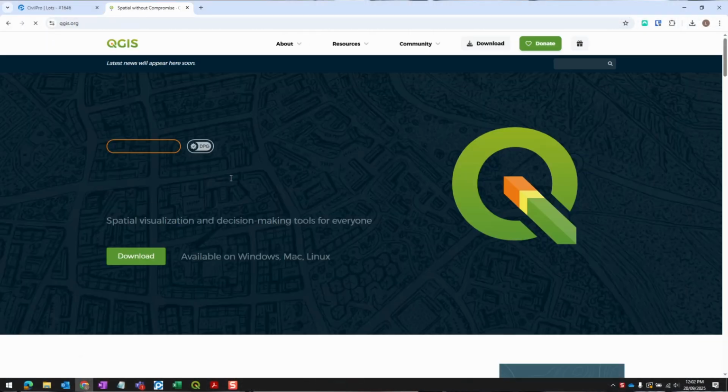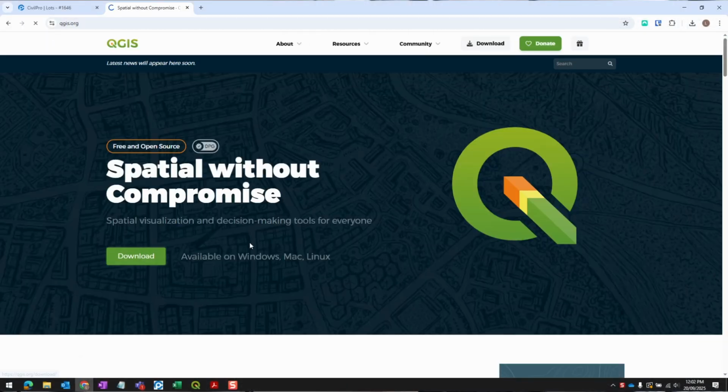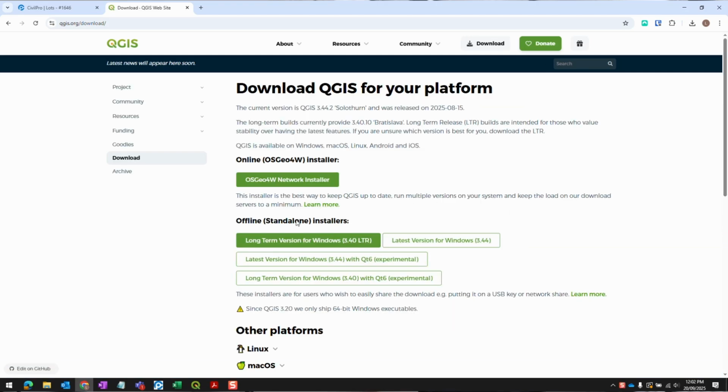I'll also be using a third-party software called QGIS, open source, freely downloadable, to undertake this geo-referencing process where we add that spatial information to our construction drawings. It is a slightly technical thing to do, so it may be worth touching base with your surveyors and asking if you can get them to either do this process or to give you guidance on this as well. I did it, so you can do it, so let's go.